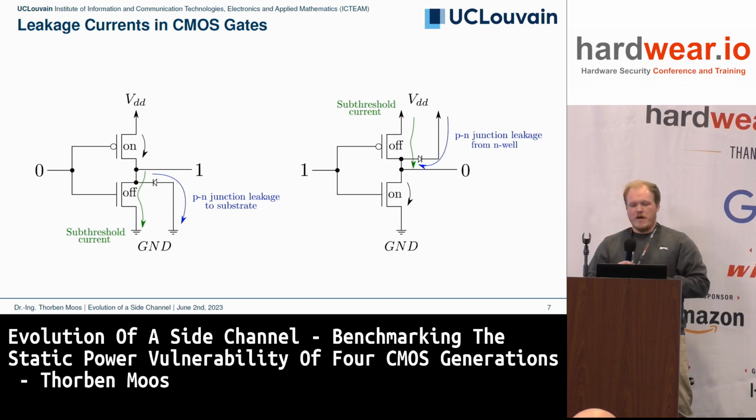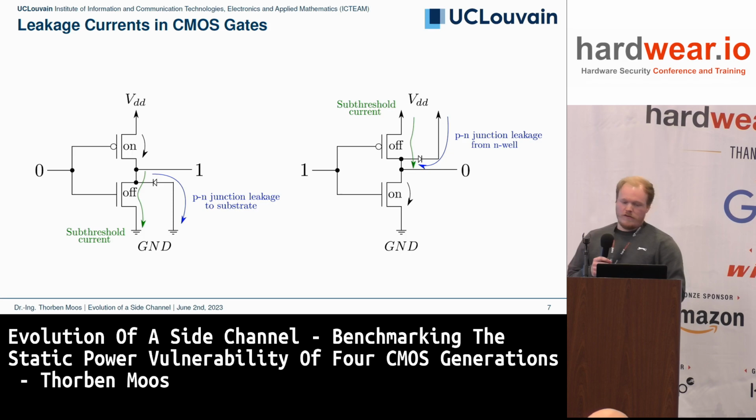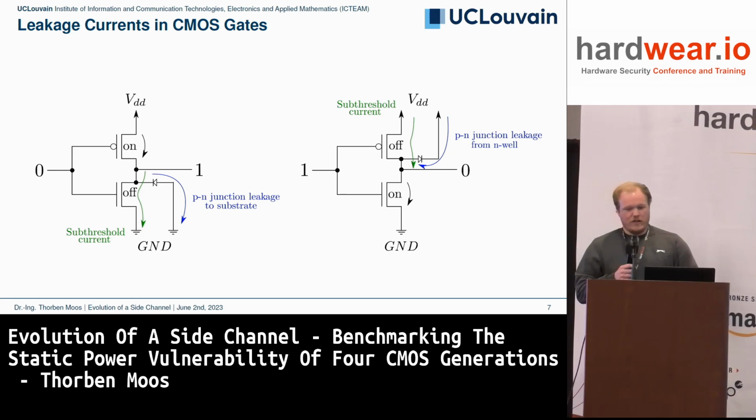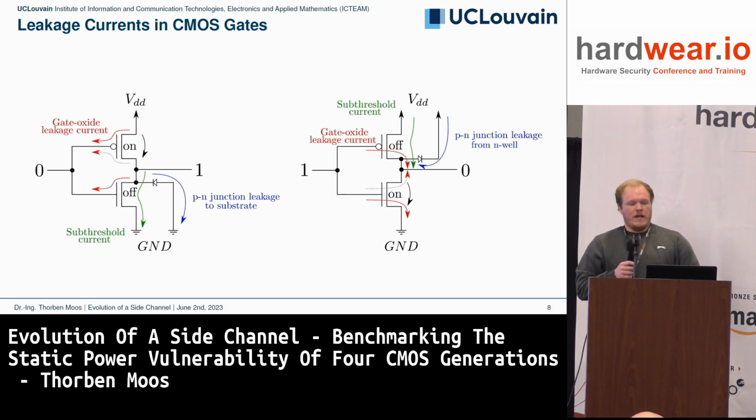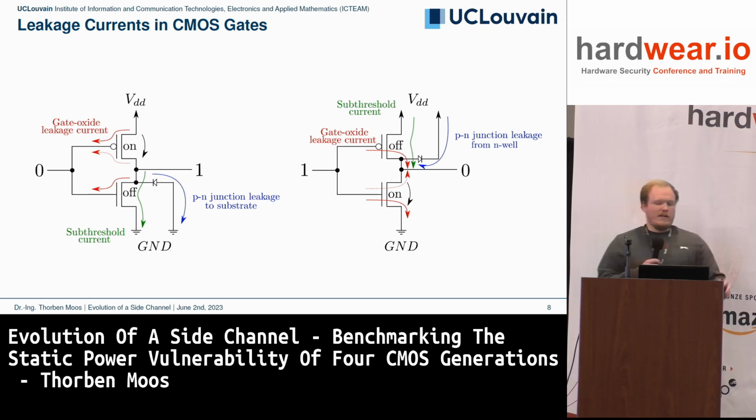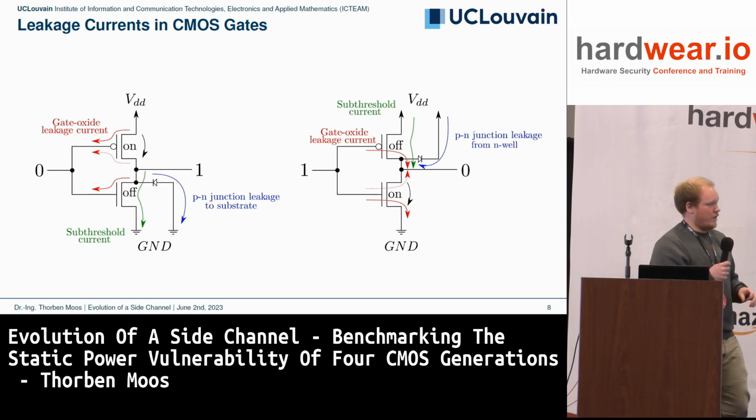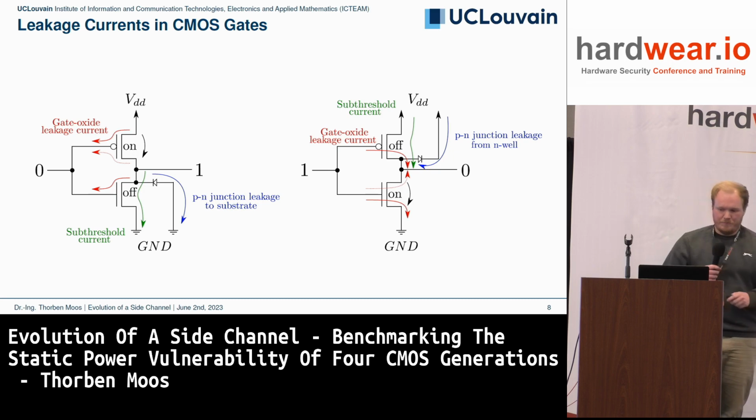We have some drop-off, and I can only decrease the voltage so much. So I still have this in both NMOS and PMOS transistors. I also have the junction leakage for the PN junction, and gate oxide leakage currents essentially everywhere there is a potential across the gate.